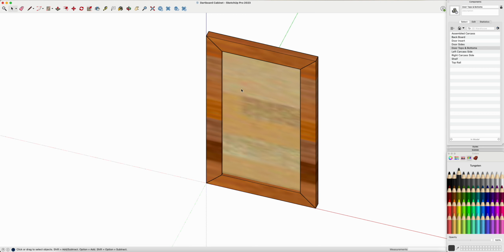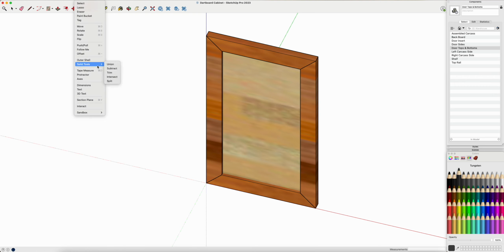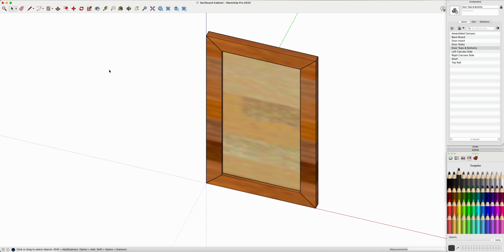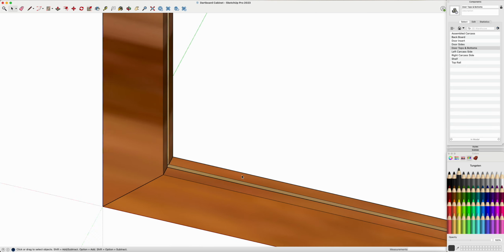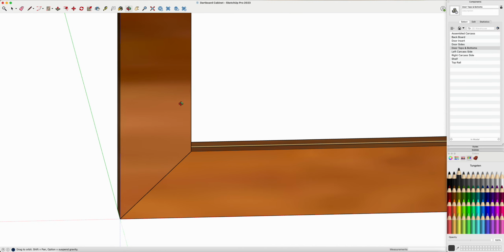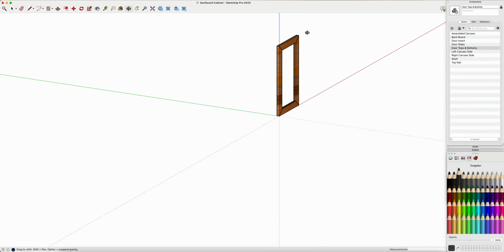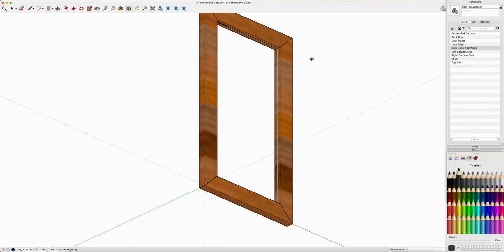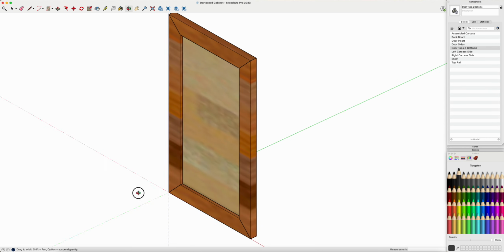Now that we've got this, we can click on our centerboard, tools, solid tools, trim, middle and outside. And what that does, if I delete the middle out, you'll see it's giving me that nice neat little rebate through the center there again. Perfectly neat, perfectly tidy, all the way around the carcass. And so I'll put that back right where I want it.